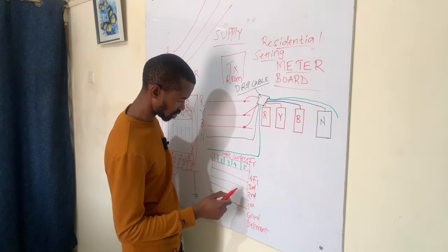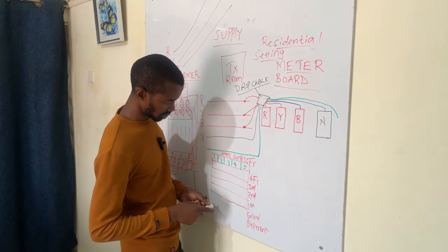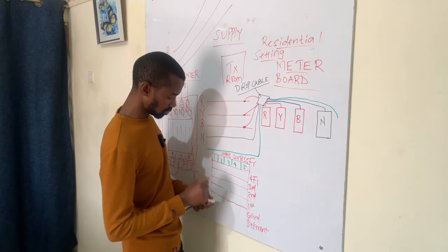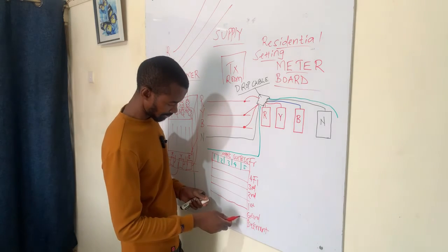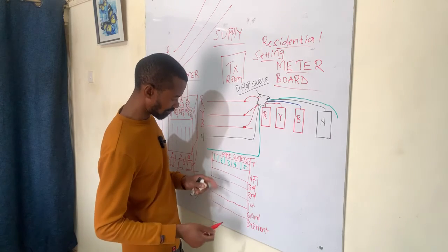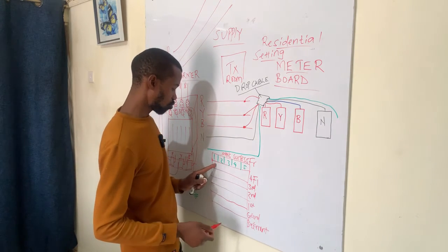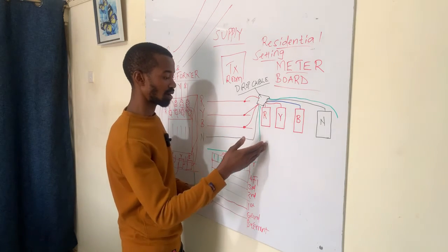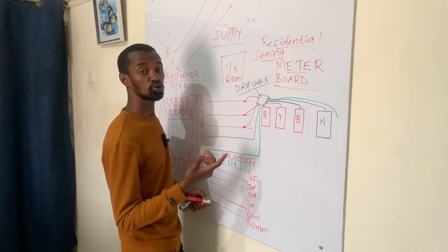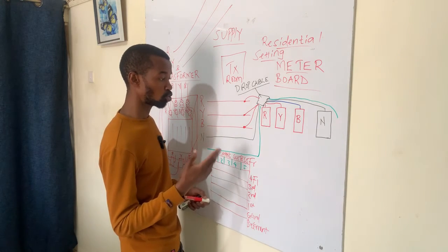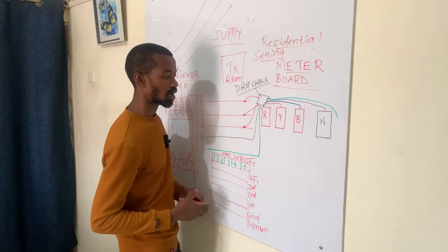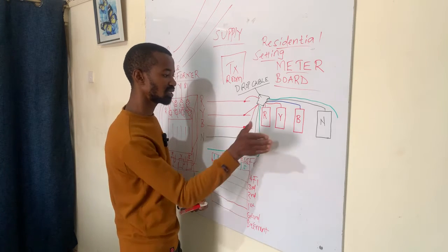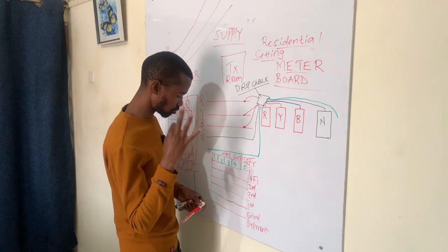There are machines which lead to those issues. So this is an apartment running up to the 5th floor. Inclusive of the ground floor, we have each floor having 5 two-bedroom units. Now we want to connect our power in a manner that we will not overload a specific phase or 2 phases, and then not balance the load to the others. So we want to distribute this demand to these 3 phases that we only have.